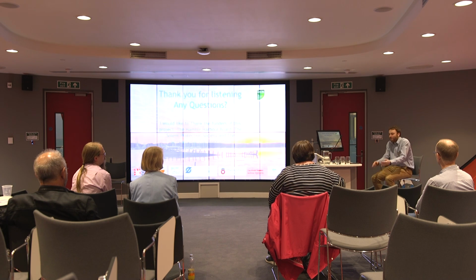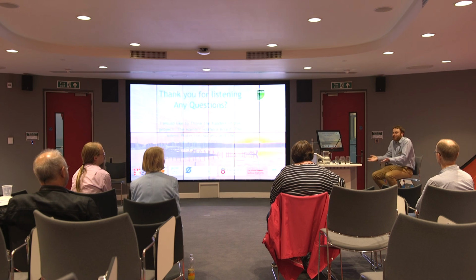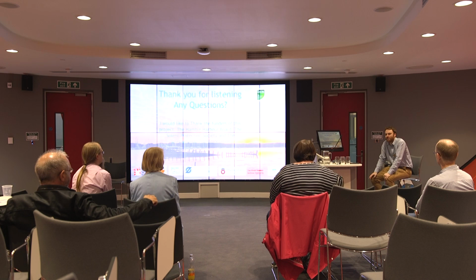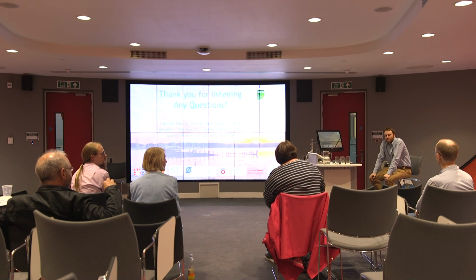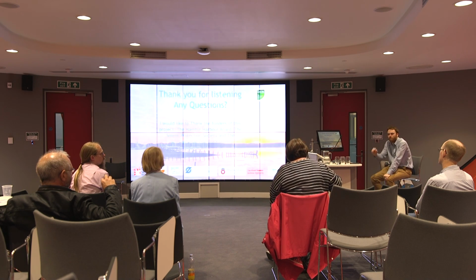So yeah, anti-fouling paints are becoming a lot less effective, and that is due to the fact that they've been made to lower the metal levels in them, and of course that is having a major impact on it actually being effective. So it's a difficult one, isn't it, where you've got the compromise of having stuff that's actually effective or protecting the environment. It's one of those balances that are hard to reach. But there's a lot of research going into how you prevent hull fouling. There's a lot of the self-polishing paint, etc.